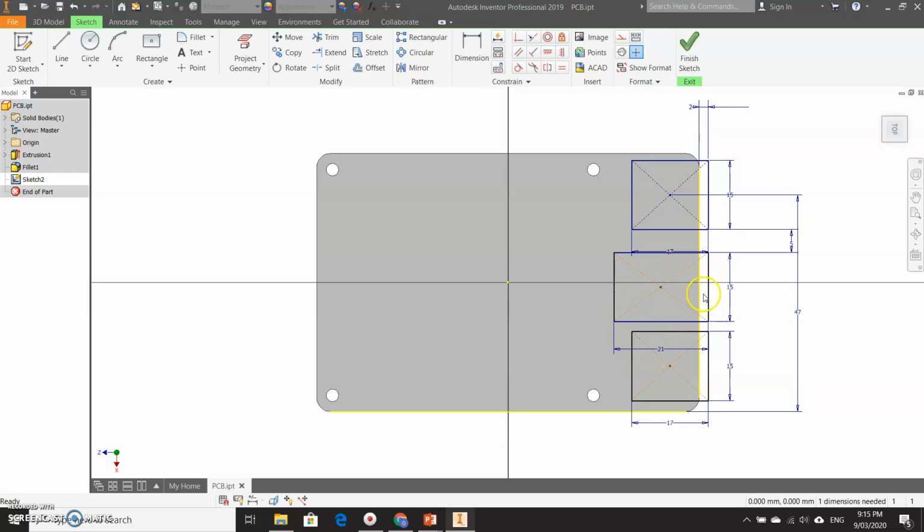So, by pure accident, what I can do now to rectify that very quickly is go Control Z. Right, so Control on your keyboard and Z is undo, and you'll find that's the same for most software. You double click on the 17 down here this time and change that to 21 and press enter. Notice the way that it stayed 2 millimeters consistently the whole way down.